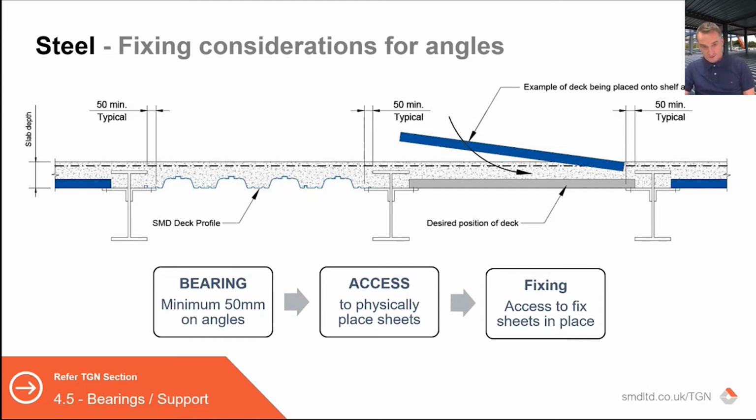The key thing from an installation of the deck, though, is to be able to fix those sheets in place, because without those fixings, you've got potential for wind uplift, etc. You also have the potential for them to shift off of bearing, which is obviously a huge health and safety issue. So they have to be fixed in place.